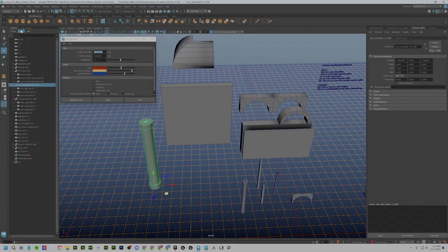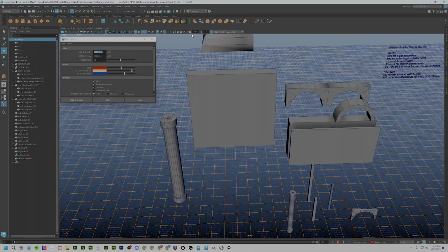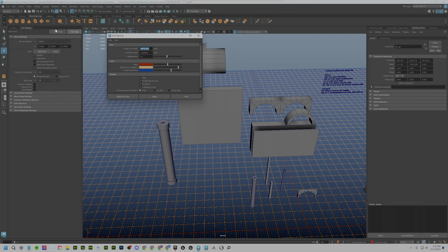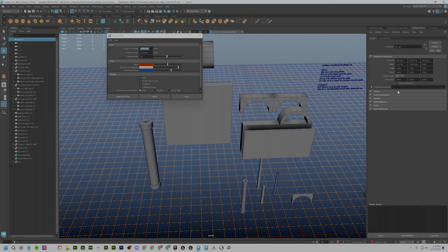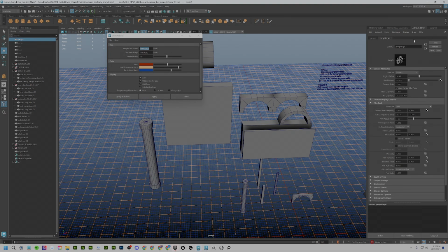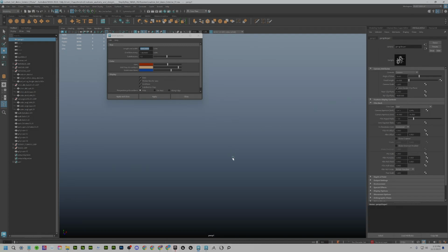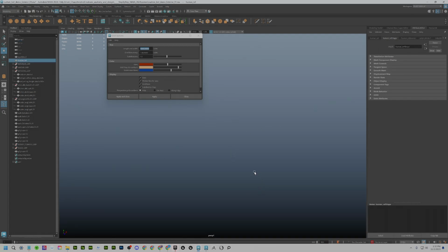The other thing is you want to go to the perspective camera and go to its attributes. After you click on the perspective camera, you'll want to go to its clipping plane. So let's find that real quick. Okay, so inside the perspective camera's camera attributes, if I go back to where it was by default, it has this really super annoying default that Maya's always had. I guess it's to save people with really crappy computers, but I've always thought it was just kind of silly.